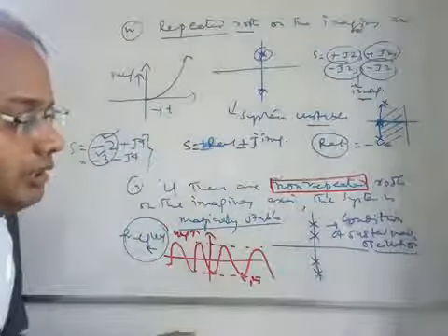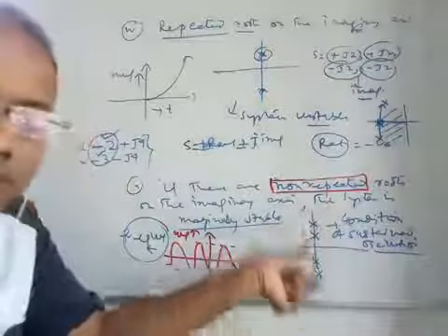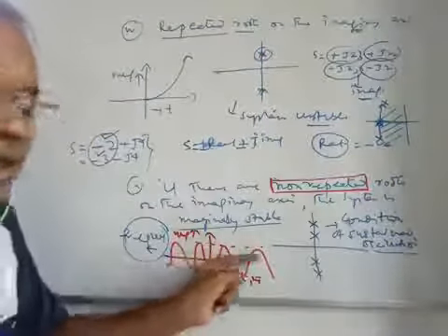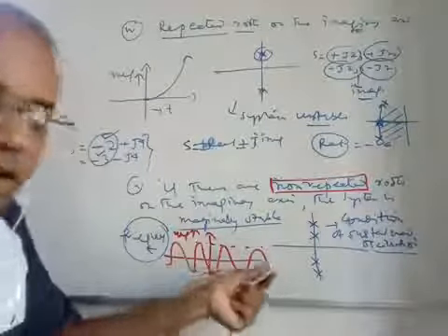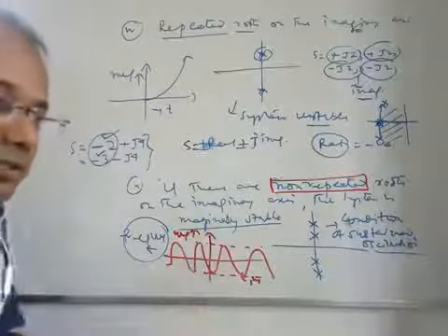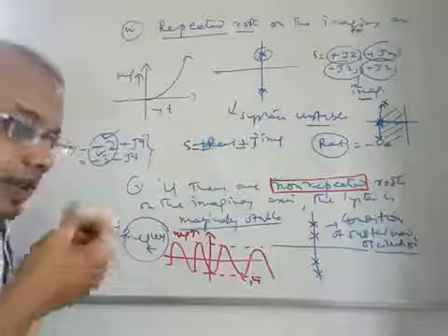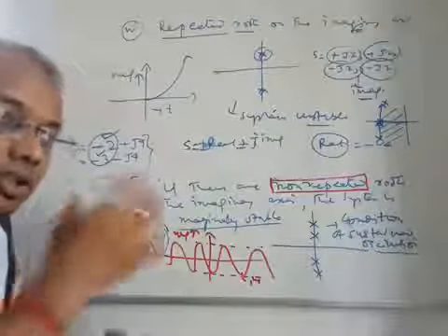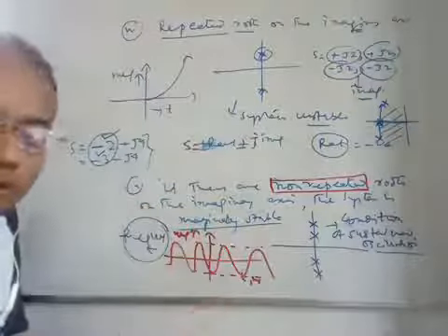And in other words, if non-repeated roots are on the imaginary axis, again this is the condition of sustained oscillation, where the time characteristic of the system is oscillating with time. This is the way the condition of BIBO stability is derived, and the condition of BIBO stability applies to the locations of the roots in the s-plane.